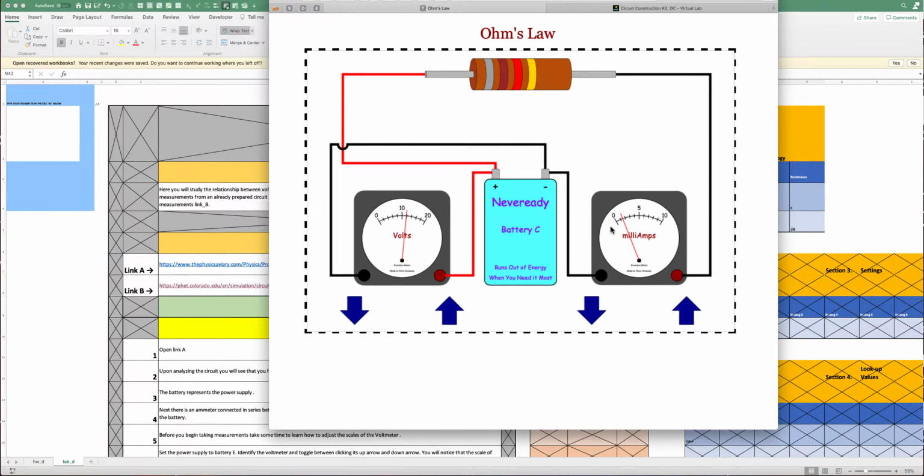So here it looks like these are different readings, but if you actually calculate those scales, for example, this looks like it's about 1, 2, 3, 4, 5. So this is about 1.5 milliamps. If I go to the next scale, now this is on a scale of 20, but let's see what this is. This is going to be 2, 4, 6, 8, 10. So again, this is a little less than 2, so this is still about the same reading. It's just that you're reading the same value, but on a different scale.